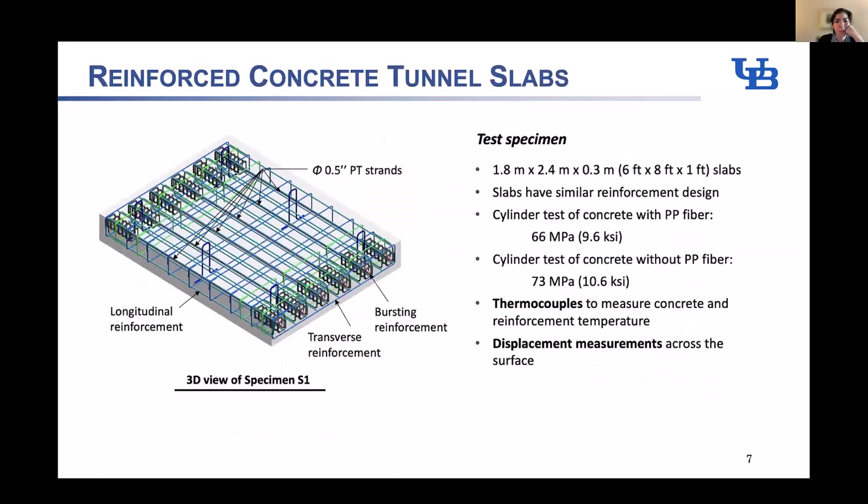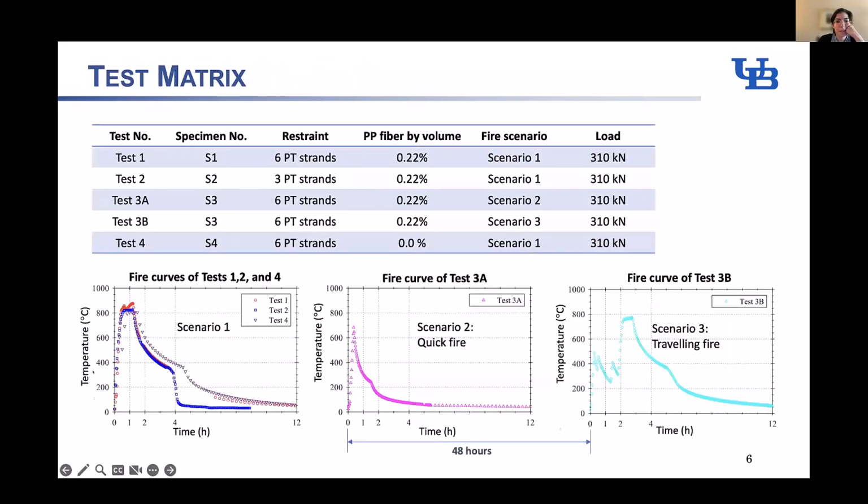Definitely. So a very good question. I'm going to go back, and here's the fire curve. Up to 12 it is completely cool at this point. It gets to 850 and then we keep it there slightly more than 1 hour. The overall test takes less than 2 hours. So that's when the furnace is shut down.